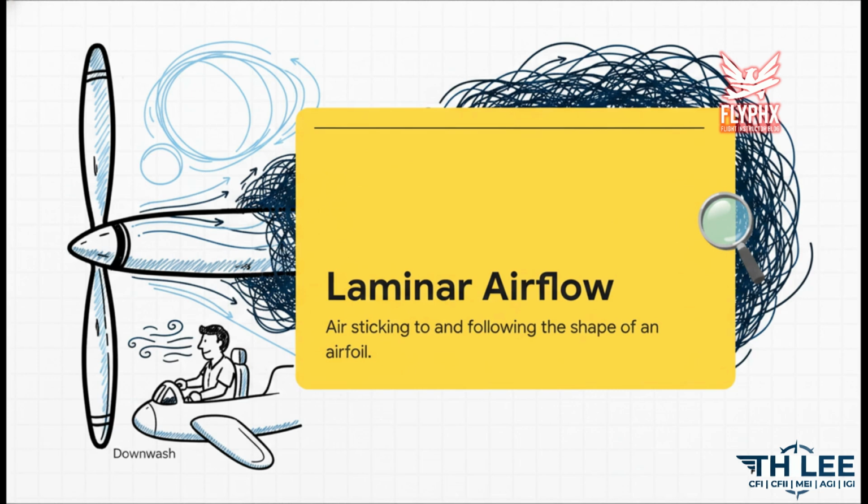As laminar airflow, that's the air sticking to and following the curve, moves over the blade's surface, it creates a void, a low pressure area on the front upper surface of the blade. The high pressure from behind naturally wants to rush in and fill that low pressure void. But, well, the propeller is in the way. So the high pressure literally pushes the propeller forward. And remember Newton's law, every action has an equal and opposite reaction. That is exactly why you feel that massive rush of downwash when you're sitting in the run-up area right behind the prop.